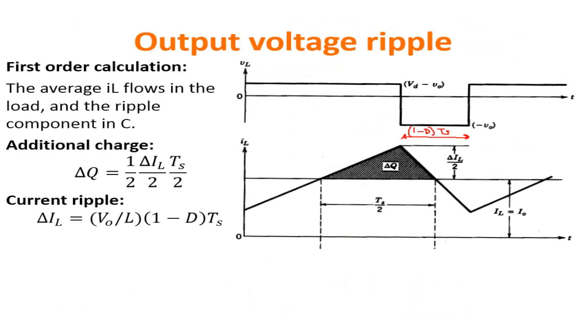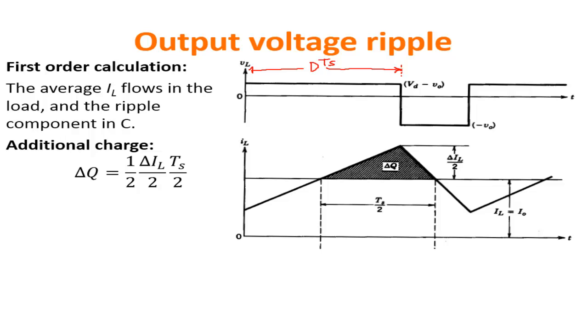Okay. Now I want to stress a bit the comment that I made before regarding the ripple. Of course, you have an output ripple. You have this switching wave that is filtered by the LC filter, but of course it's not filtered completely.